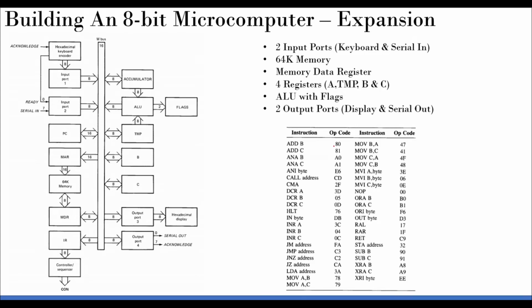So this memory location, 64K locations are having 8-bit as the output, and the important thing is the instruction itself is now 8-bit. Earlier it was how many, 4 bits, right? Now it is 8-bit. So you can see it over here. Add B, for example. So this is a complete instruction now. Add B is 80, add C is 81. So you can easily decode that add is nothing but 8, and B and C are denoted by 0 and 1. This is hexadecimal again.